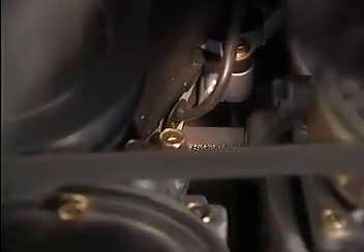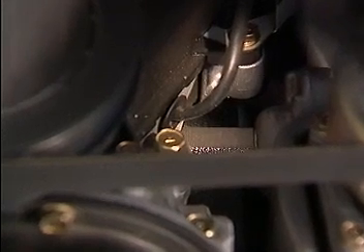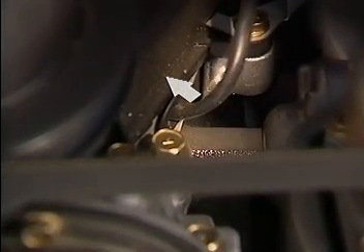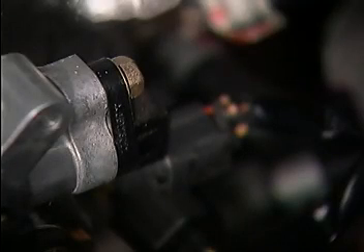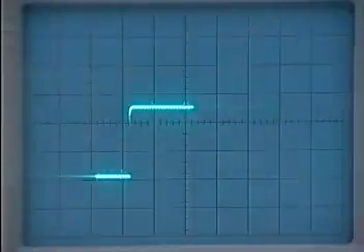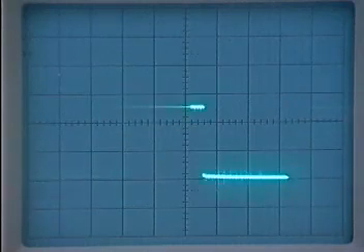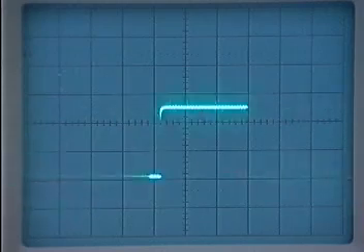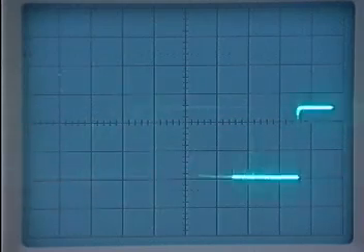The ignition system crank position sensor is basically the same as the 2.0-liter turbocharged engine used on the Eclipse. The camshaft position sensor is located at the rear end of the cylinder head. It's mounted on and rotates with the camshaft. While this Hall effect type sensor produces a square wave signal similar in design to other Mitsubishi camshaft position sensors, the signals are generated differently.